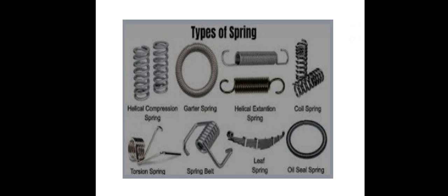Conical spring and volute spring. Conical and volute springs are used in special applications where a telescopic spring, or a spring with stiffness that increases with load, is required.